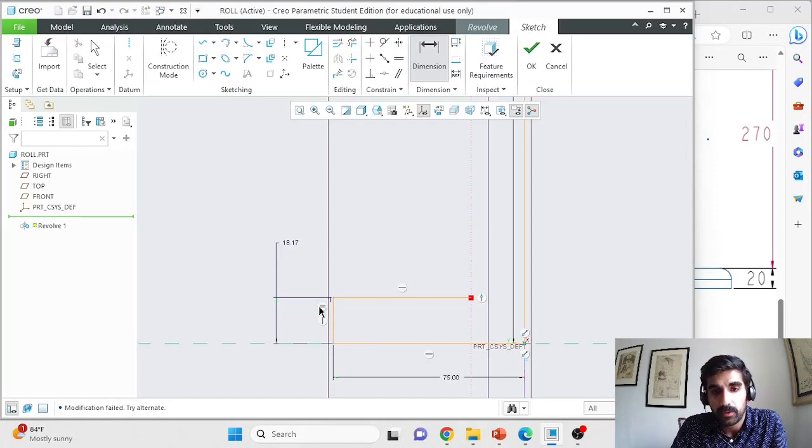We haven't spoken about this, but these symbols over here are different constraints. Somehow, while making this line, I gave it a constraint that this line not only needs to be vertical, so this symbol means vertical, and this is where you can prescribe constraints from. It also has to be equal to some other feature that exists.